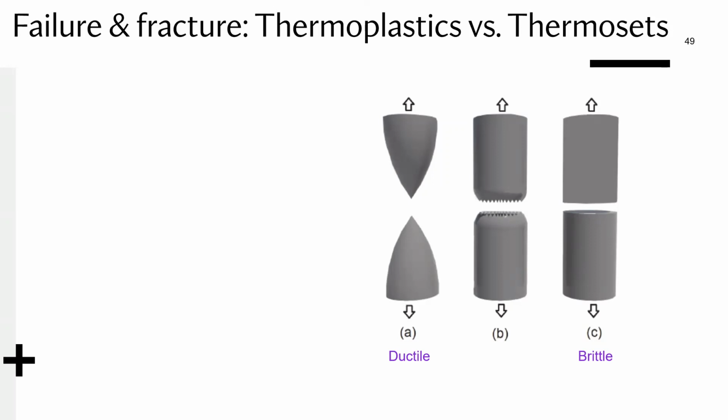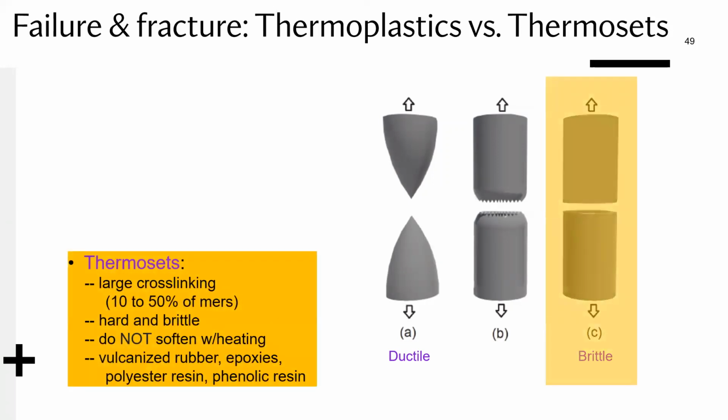So when it comes to polymers, thermosets are known as very highly cross-linked materials. They're known to be rather hard and brittle. It's usually irreversible cross-linking, like resins and other sort of epoxies have. And so they become quite highly cross-linked and therefore quite brittle.